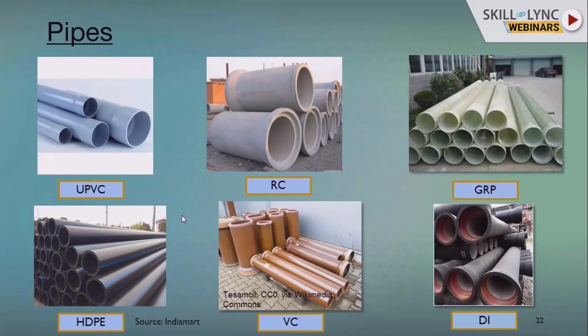Although the contractor and subcontractor say, I don't want to use this RC pipe because it is difficult to install, it's not easy, as a designer we always force them to use this pipe. There is another pipe you can use, GRP. The good thing about GRP pipe is it is very easy to install. It comes in a big length, around 12 meters, so you can install it very easily. But the problem is it is not heat resistant. If there is so much heat, this pipe degrades and you can hardly use it for 30-40 years. This is the main problem. So generally these are the pipes.